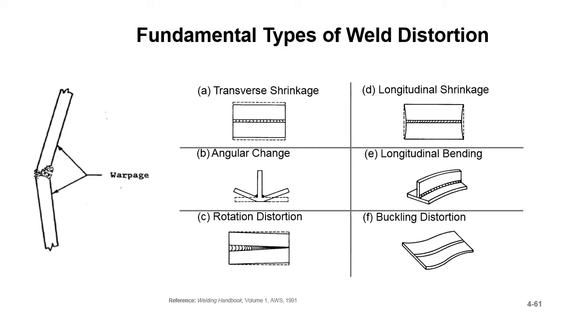So buckling distortion. The U.S. Navy worries about this a lot on ships. They're welding a lot of thin materials and long sections, and ship makers in general. When the weld cools, it pulls, and you have this buckling distortion. It looks like waves in the metal. This is a phenomenon that generally occurs only in thinner materials. You're not going to have it with 3-inch plate. It's 3/8 and under generally, I'm thinking. Don't hold me to the 3/8, but I know at 1/8 inch you can get this pretty easily.